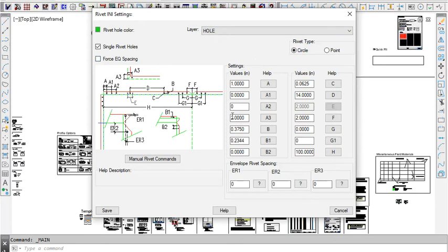So once you've locked down what your rivet spacing is supposed to be, or pilot holes as some people call it, then that particular project INI, you don't need to set it every time you go into a project. You just copy your core project INI to start your next job, and then you copy it and just start the next job. So you're only changing the things that need to be changed, like the customer information, the material selection, and the location of where these output files are going to go. Like basically, where's the project folder for this particular job, and then you move on.